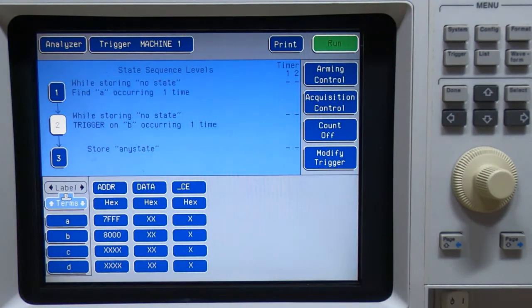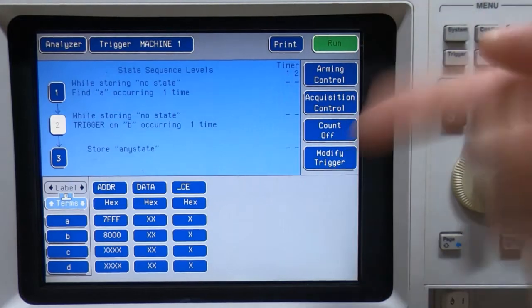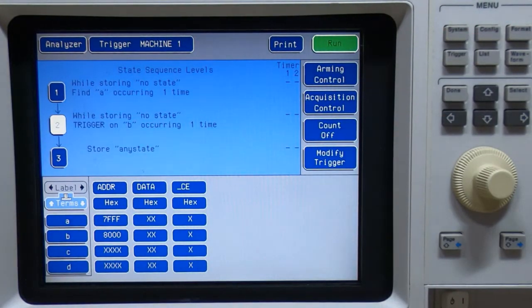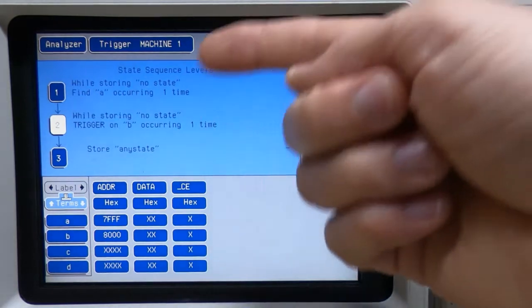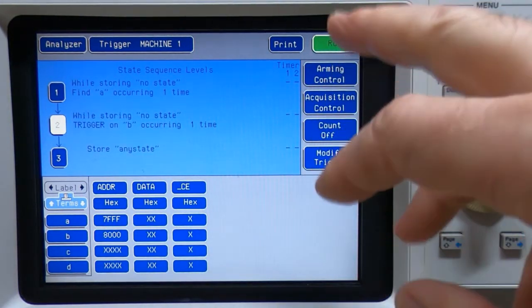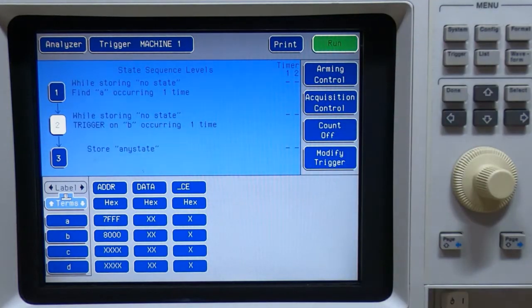It will then store all the data it's captured in the process, and it will then stop. So though it's always capturing data, it will only bring all that to a halt once it hits the trigger. So you can put the trigger anywhere you want in the sequence. Just bear in mind that once you hit the trigger, you're effectively bringing an end to the process. Well, at least it's the start of the end, so to speak.